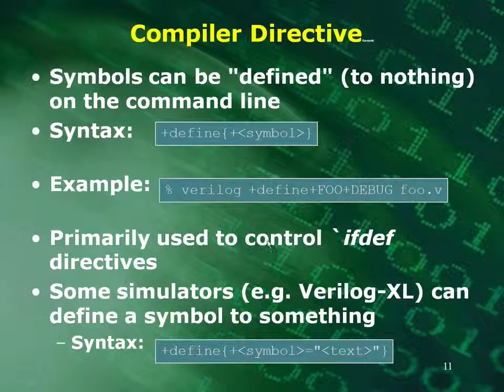So they're primarily used to control ifdef directives, whether you're going to include one code or another or some other code. And some simulators can define a symbol to a particular text string, but not all of them can. In this case, this is Verilog-XL, and they allowed it.